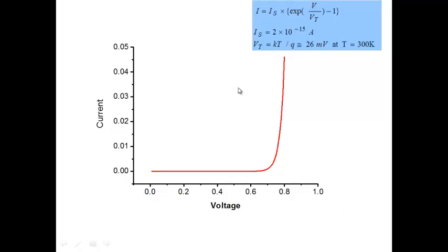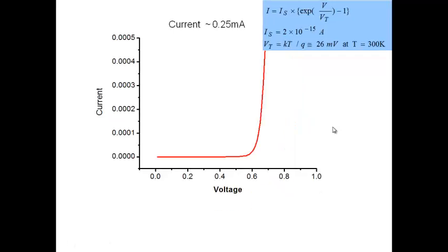Again, you can see it if I take my exponential over a current range from 0 to 0.05 and I approximate it, we get V gamma of 0.75 and a resistance of 1.4 ohms. Right? It's an approximation. If I approximate it over a different current range, I get a V gamma of 0.63 and a resistance of 150 ohm.